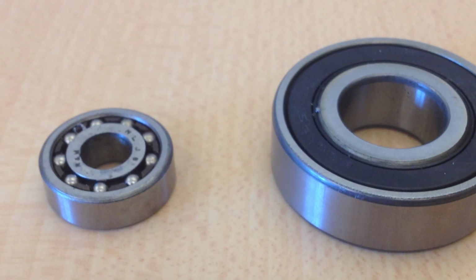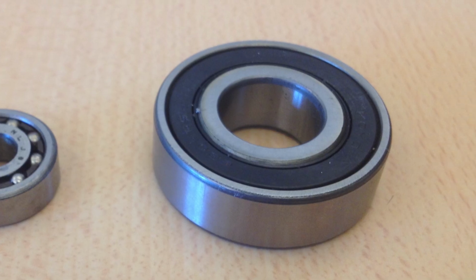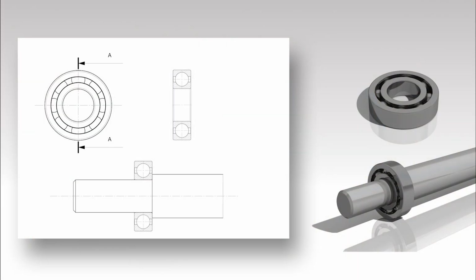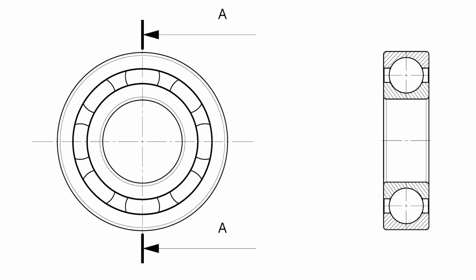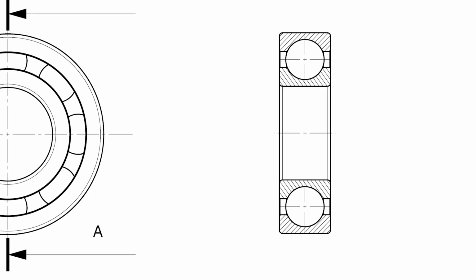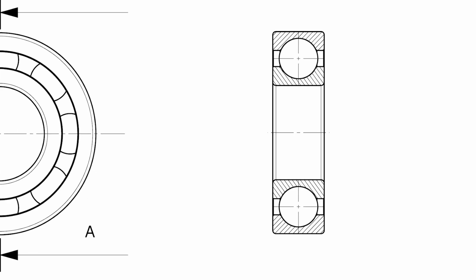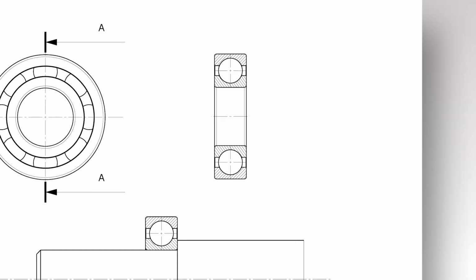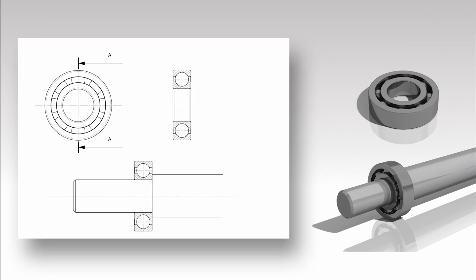Bearings are commonly used in any structure in which a part rotates. A section of a ball bearing should be drawn with hatched areas to indicate the inner and outer rings and circles representing the balls. These circles may not be hatched, just like bolts, webs, and spokes. Drawing all this detail is time-consuming, so a simplified representation has been internationally agreed.